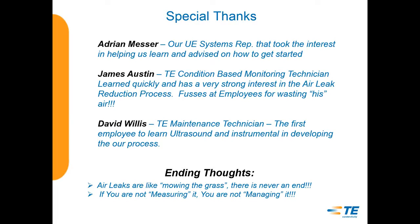People get in a hurry, they plumb up 2 or 3 things that they think are temporary, and then a month or 2 later they're permanent. They forgot they didn't put a wrench on it or didn't put any Loctite on it. So I would say the biggest thing is awareness, making sure everybody understands how expensive compressed air is and how important it is to plumb something up right to start with rather than having to pull it apart and redo it.